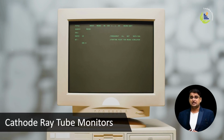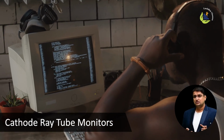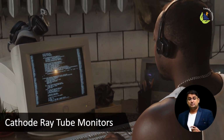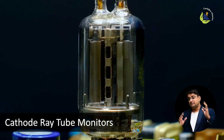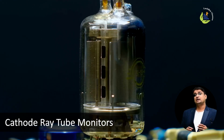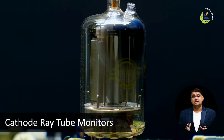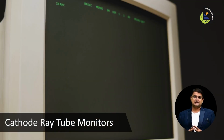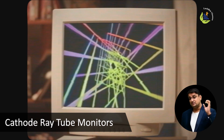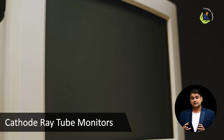Cathode ray tube, that is CRT monitors, a type of display device that uses a cathode ray tube to project images onto a screen. The monitor consists of a large vacuum tube with an electron gun at the back, which emits electrons toward a phosphorescent screen. When these electrons hit the phosphor-coated screen, they cause the phosphor to emit light, creating the images that are displayed.